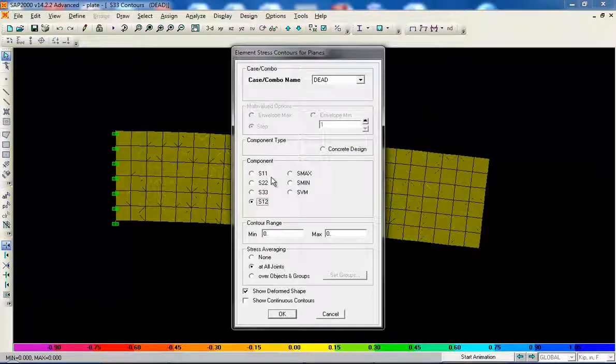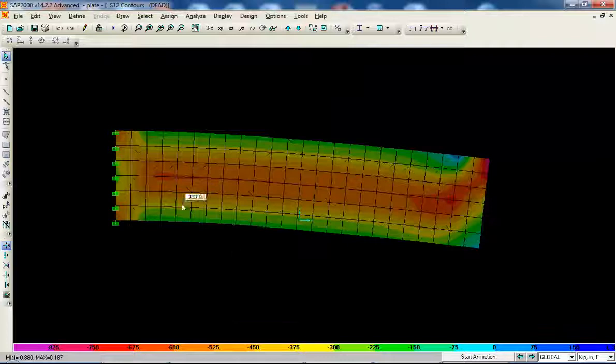Then this is shear stress, and you can see it's actually pretty nice. Yeah, it's pretty small here, then goes up, and then it is maximum at the center, then it goes down. Remember what the shear stress distribution is in your classical beam theory? So this kind of imitated that, and you can see that from here to here, it's the same, because the shear force is the same. And there's some distortion here because of the local stress concentration again.